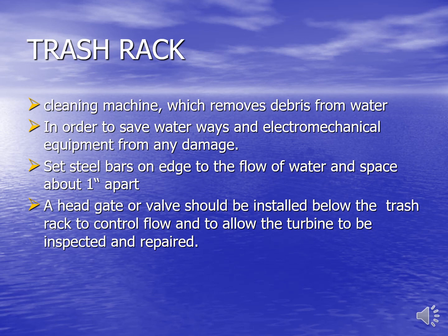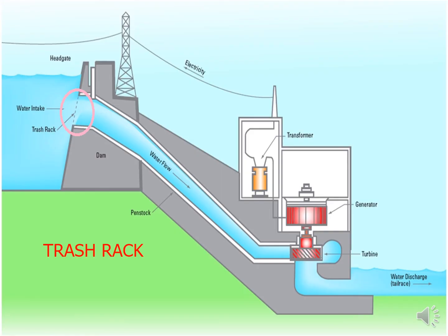It is like a grille made of steel bars, with a distance of 1 inch between two bars. So you provide the trash rack at the water intake so that we can remove the debris and control damage to any mechanical parts.